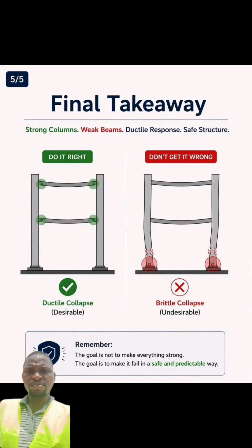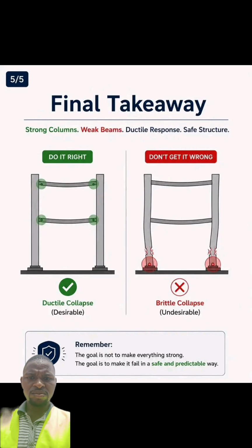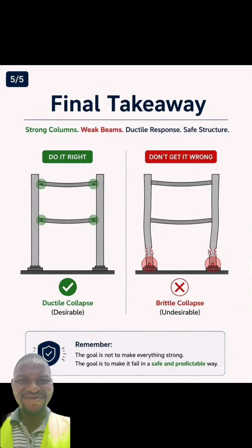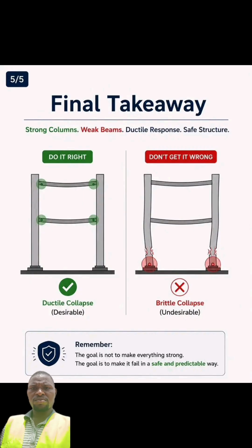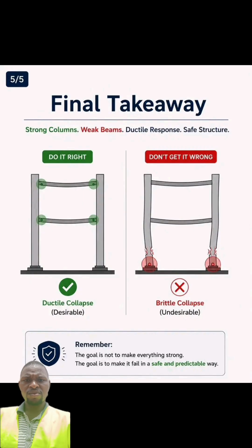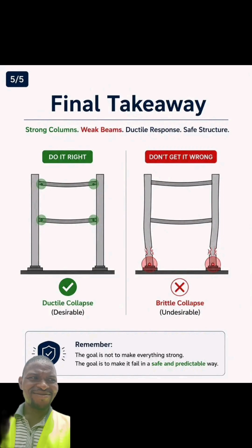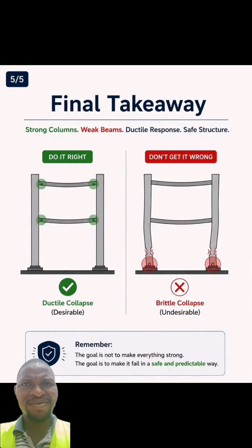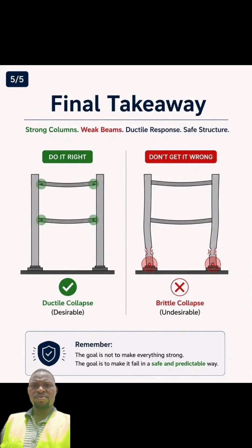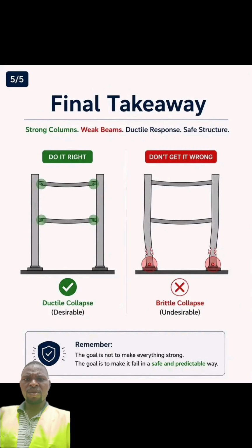on the wall from the beam section. So it shows that there's an inevitable collapse coming, and it helps people to evacuate such a building before the said collapse. So strong columns, weak beams is a practice engaged in by engineers which helps make construction safe. It helps engineers to construct buildings that are safe, giving people room to evacuate the building before any eventuality occurs, right?